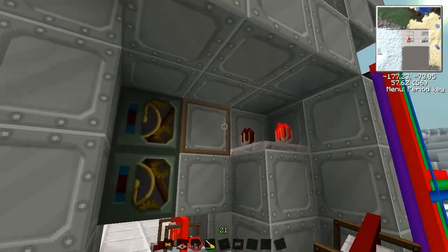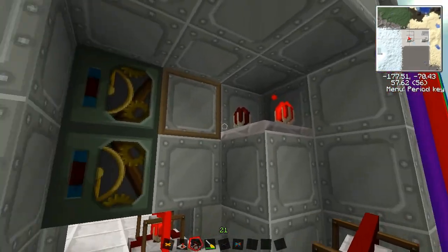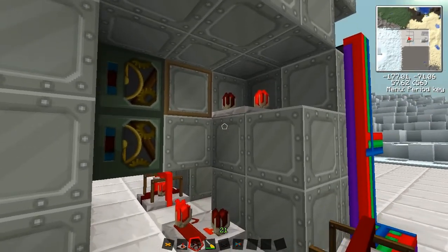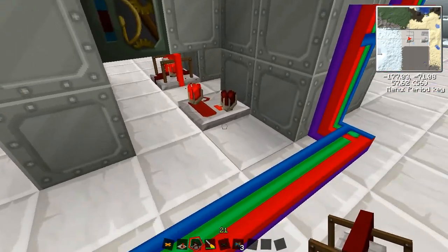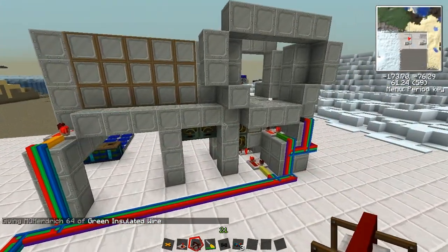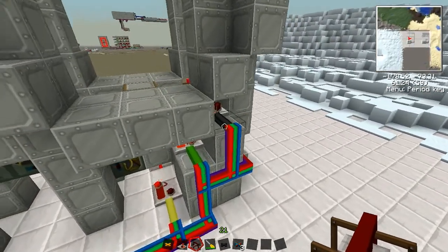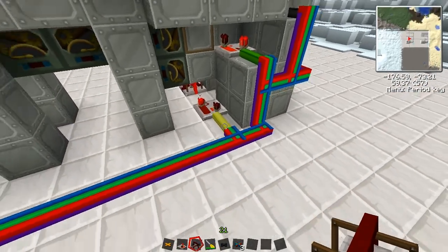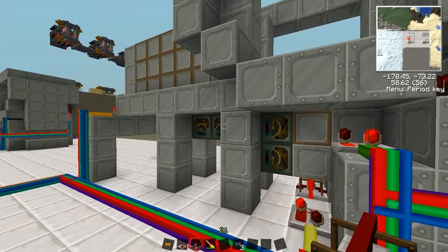Cool. So that block that we put onto the side of the platform that goes up and down is for this circuit here, which marks wiring in now. That detects when the floor is in the up position, and then when it lowers, this block completes this circuit for the lower position. Okay, so our 4 wires so far that we have going into this bundled cable: orange for the open sensor, black for the closed sensor, and then for the floor platform, green for raised, yellow for lowered. So next, I suppose we need to wire in these motors.